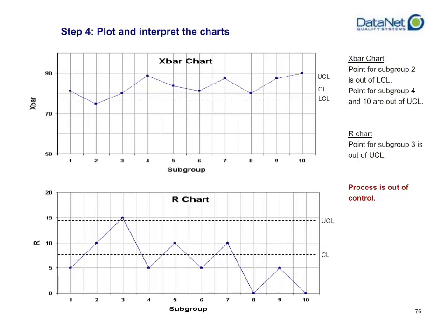And just eyeballing the trend after that, it looks like things were getting worse from subgroup 1 to subgroup 3 with regards to volatility. But all of a sudden, maybe a change happened in the middle of that subgroup, around 11 a.m., and then things started getting better, and your volatility goes way down until you actually have no range, no variation at all, on subgroup number 8 or subgroup number 10. So the volatility within your process seems to actually be getting better.